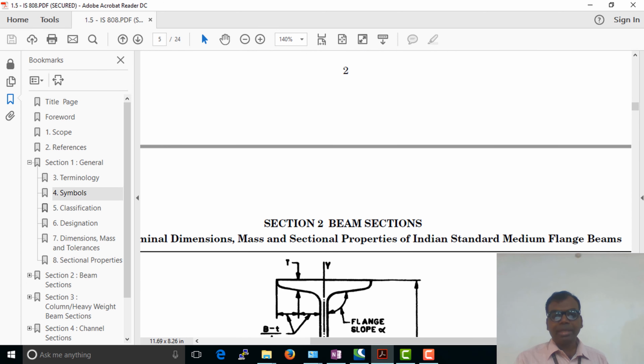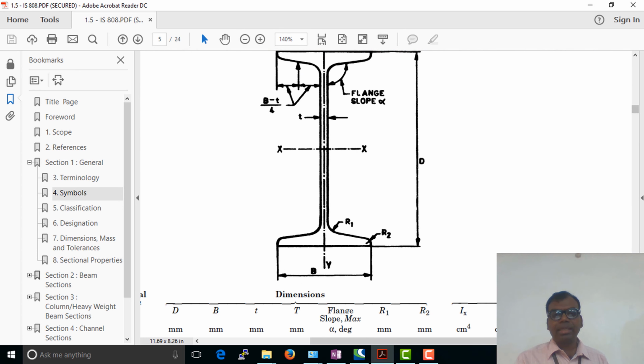Okay, coming here, if you look at this steel section, this is a rolled steel section. This is the web of the section, and this is called the flange of the section. If you see, it is not a right angled section. These are advantages because it will not allow water to stay, but the problem will come when you try to bolt it.